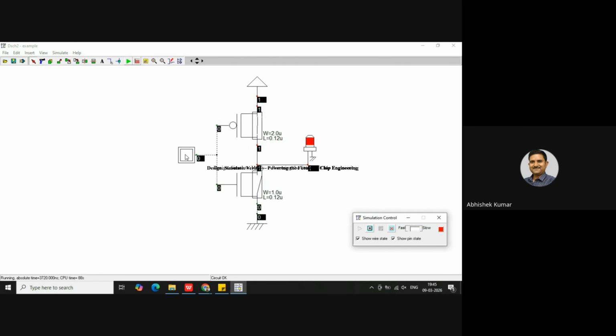Now if I'm going to change my input, it provided the one input. One input means what it says. PMOS becomes off, open connection, but NMOS becomes closed connection. Now, due to the closed connection, what are we learning now? This output is connected to drain, going to ground.